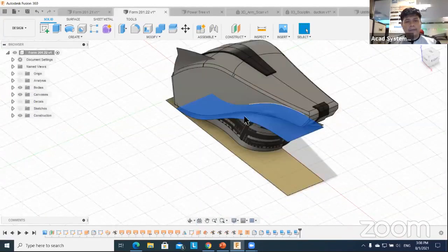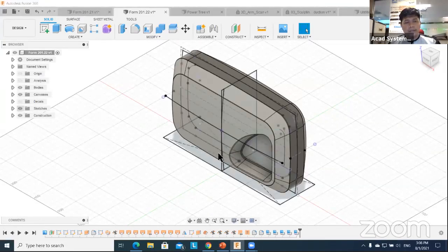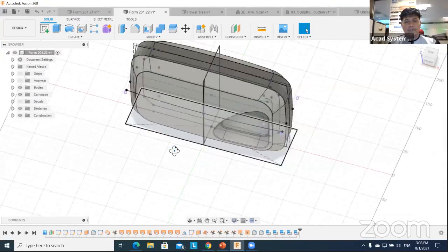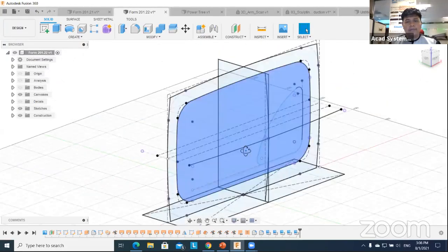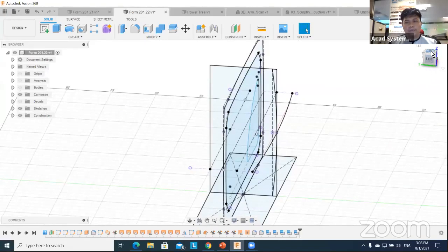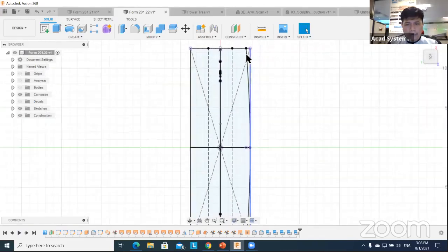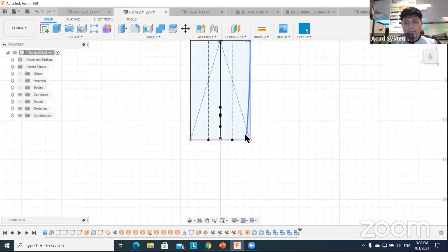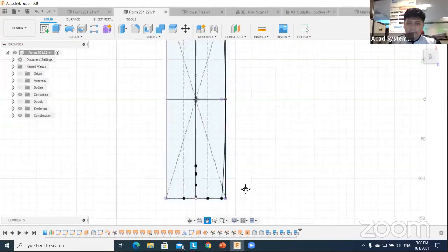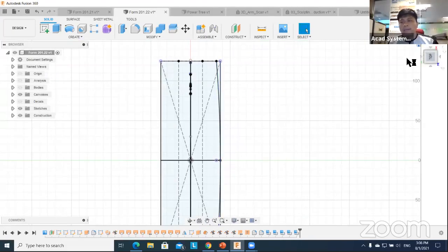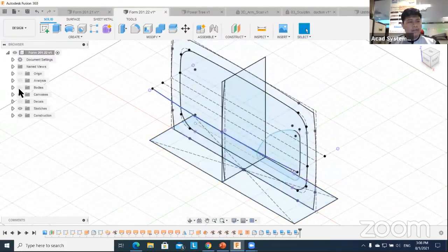For the second example, it will be this type, which also includes a combination of drawing, the point and so on. So this will be your sample of drawing. When you do extrude for your drawing, it's quite impossible to make your drawing have an angle something like this. So the normal method is that you need to create the extra and extrude cut. But using freeform modeling, you can directly create your 3D something like this.